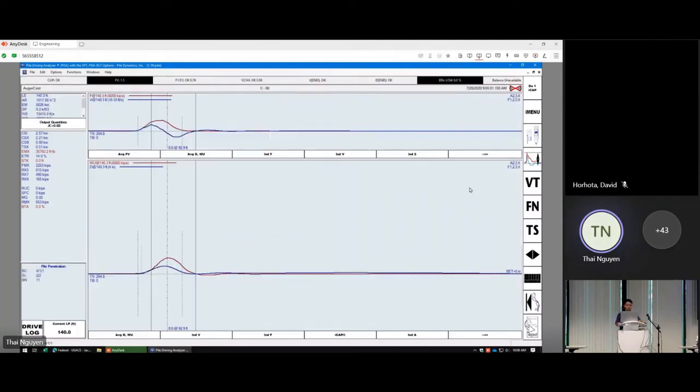So this one has incredible unloading. So the toe is here. In this example, T0 is picked up correctly. So T0 is right, toe is here, but incredible unloading. And PDA will show a beta of 0 because of that unloading. But the pile is good, perfect.